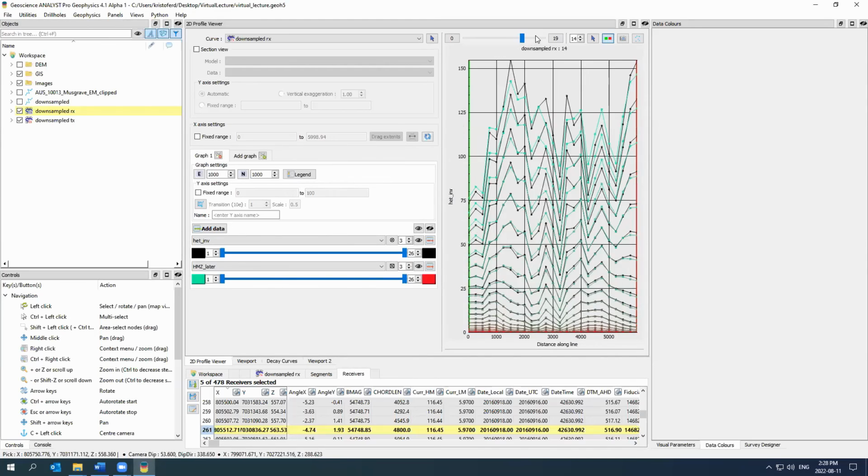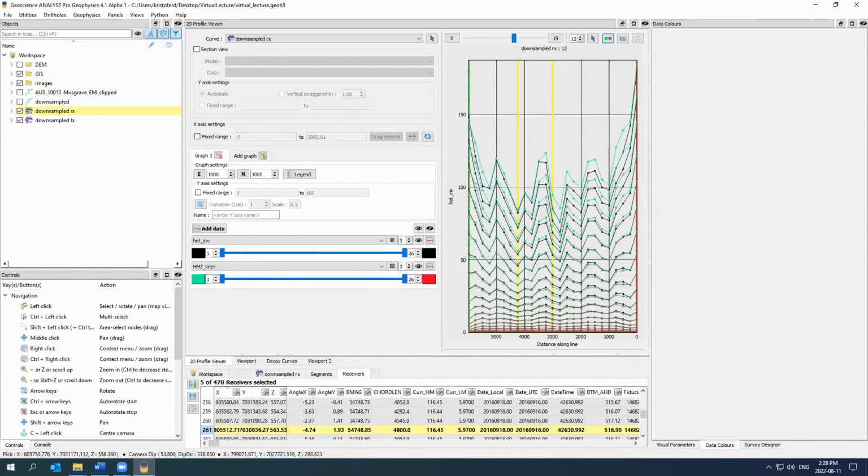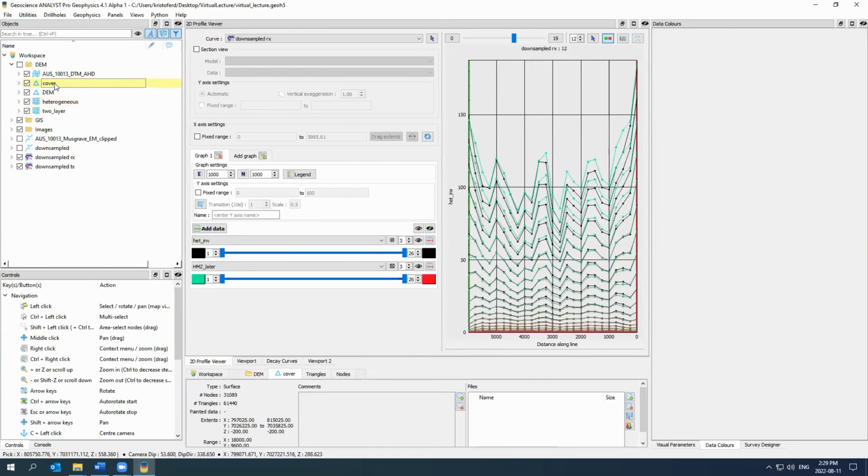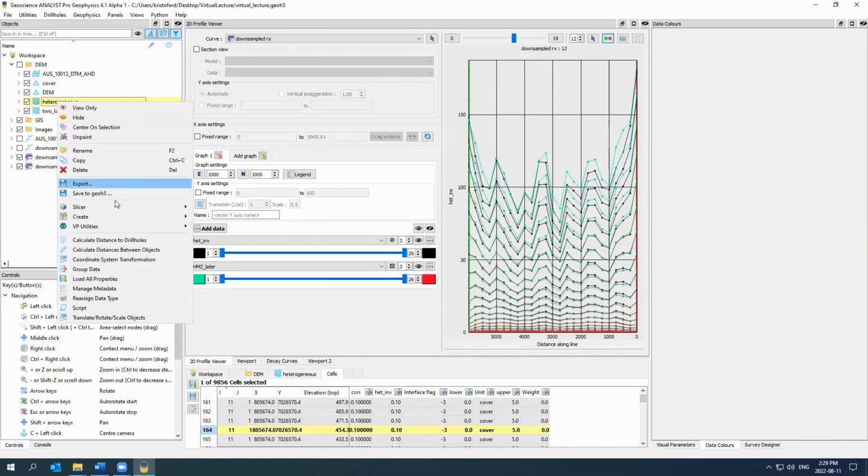And there is another question there, Chris. If you already have a cover thickness or basement topography layer, could you bring that in as surface? Absolutely. So what you can do is when you create your model, that is where your geology that you know or think you know will go. So if you had an actual thickness of cover, as long as you could create a surface from it or have a surface from it, you can absolutely create that layer in there.